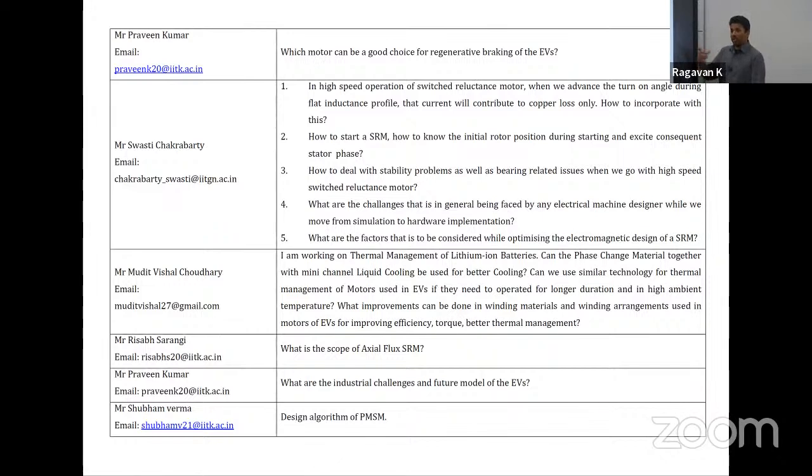That means all the current is coming through the winding. Maintaining that 0.1 to 0.2 millimeter air gap is also challenging, because here you don't have a bearing holding it in place. You have a linear bearing that's holding it in place. So it's a little bit of a challenge. It's manageable, I would imagine. People have done that, but I haven't seen any application. Even appliances, I haven't seen that being done. Axial machines, PM axial, I have seen, obviously YASA and such is axial.